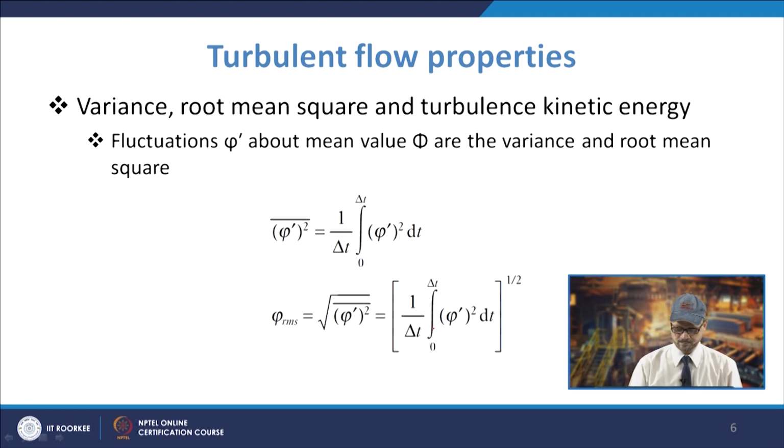Before that we need to understand that u prime square, v prime square or w prime square, the bars on all these components, give rise to some of the stress terms. These stresses, which are because of these fluctuation components, we call Reynolds stresses, as we discussed.